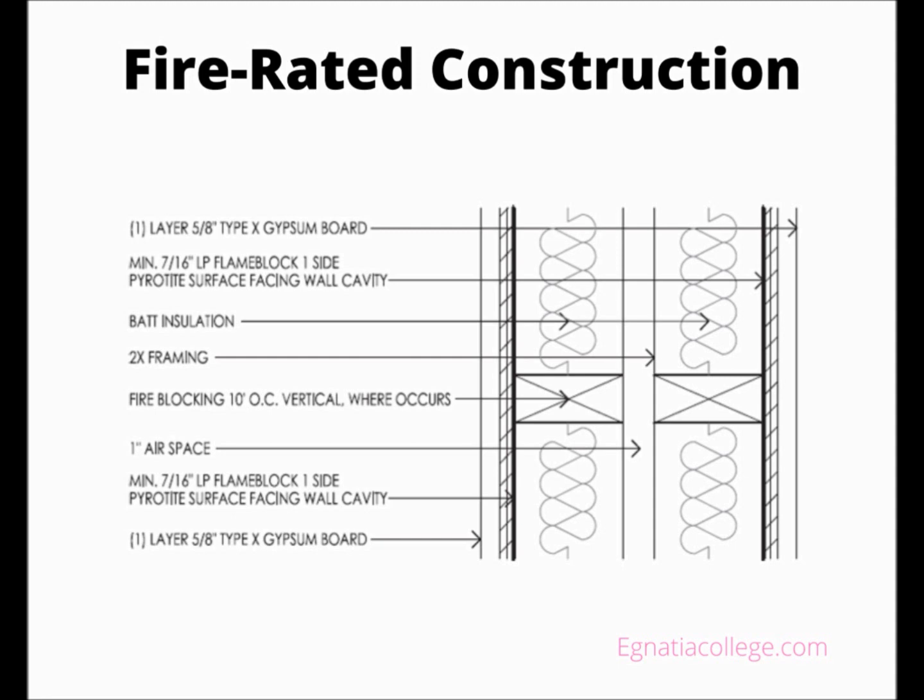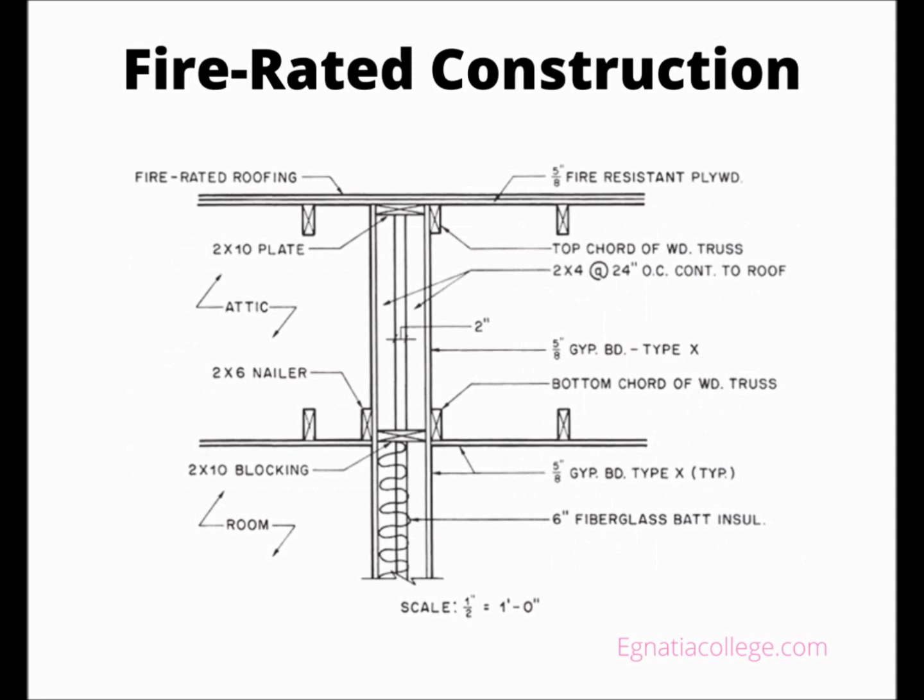They do not burn, and they do not easily transmit the heat of fire to the framing members on the other side. Unfortunately, standard gypsum wallboard breaks down and crumbles in very high heat. Fire-rated wallboard is used where a fire-rated wall is required. Fire-rated gypsum wallboard is Type X or Type C wallboard. Varying degrees of fire resistance can be achieved by using a second layer of fire-rated drywall on one or both sides of the wall. Other materials, such as OSB, can also be used if treated.